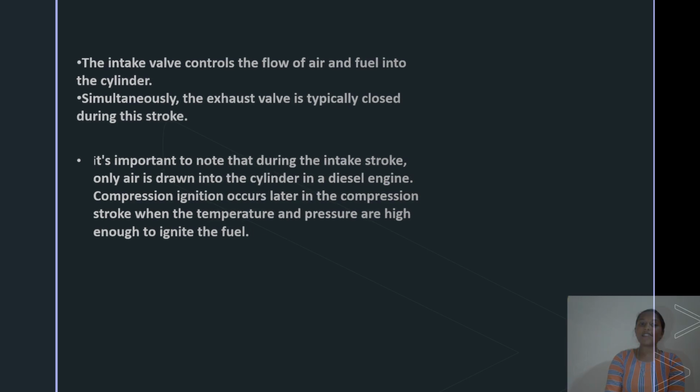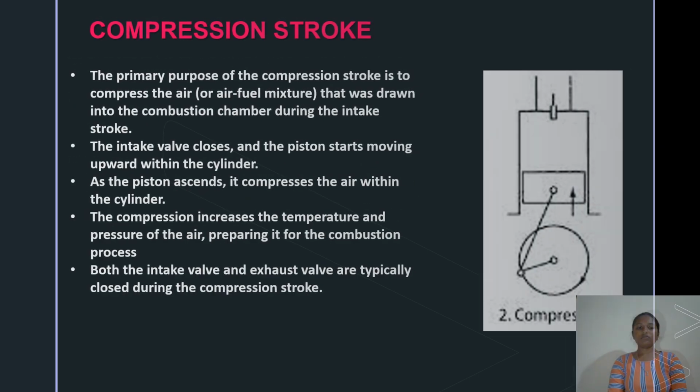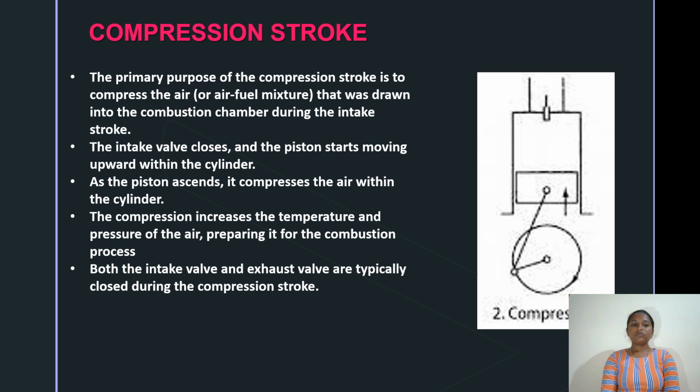Next, the second stroke is compression stroke. The primary purpose of the compression stroke is to compress the air which was drawn into the combustion chamber during the intake stroke. During this stroke, piston moves from bottom dead center to top dead center. Both the valves will be closed.